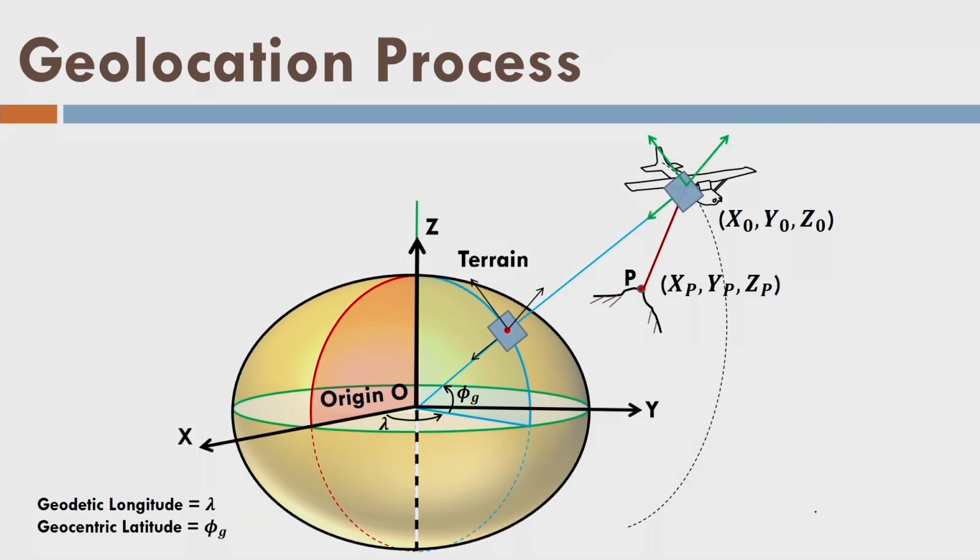Again, this is the ETRF frame. So, true north, true east. This is a 90-degree angle, and now I want to bring this earth tangential reference frame to the geocentric reference frame. This is the z direction here, and what is the angle here? This is the phi g angle, which is written here. So, the total rotation about the y axis between the z axis of ETRF and the z axis of the ITRF is equal to 90-degree plus phi g. So, let us do the rotation about the y axis like this, 90-degree and then 90-degree plus phi g. The z axis is aligned now.